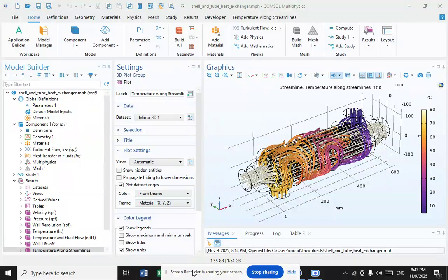The recovery of heat from low temperature systems requires different working fluids than steam. The organic Rankine cycle, or ORC, waste heat recovery unit can be more efficient at low temperature range using refrigerants that boil at lower temperatures than water. Typical organic refrigerants are ammonia, pentafluoropropane, and toluene. The refrigerant is boiled by the heat source in the evaporator to produce superheated vapor.